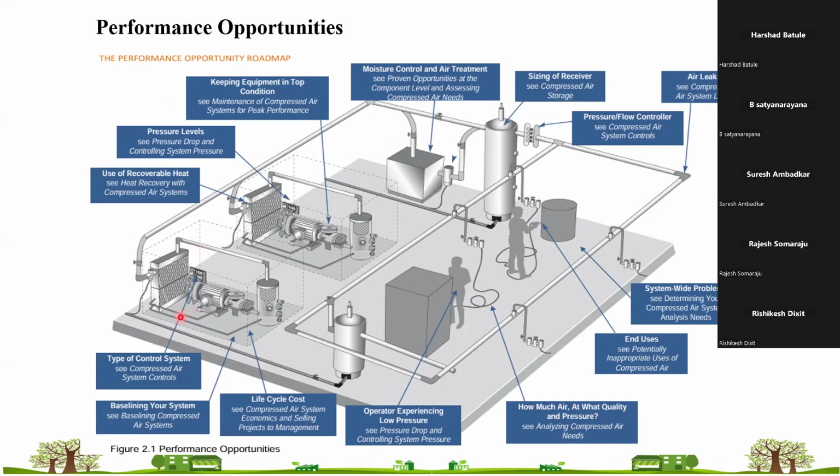Then baselining your system, like kW per CFM. The kW per CFM of a compressor has to be your baseline, whatever the standard operating conditions are for that particular compressor. So that should be in operating conditions also.